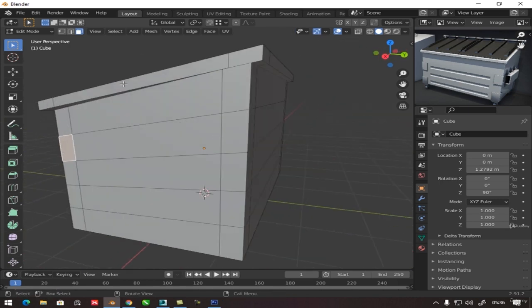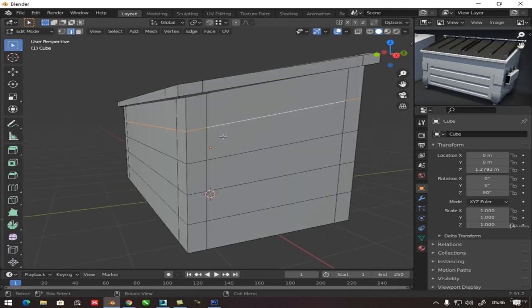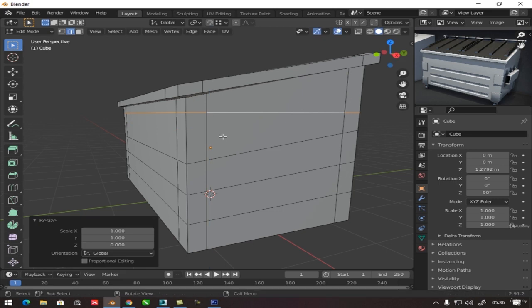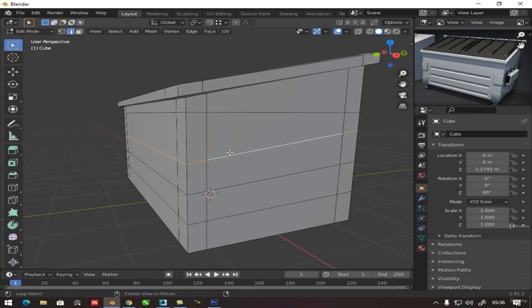Now, in this face, I'll get this face, but it's inclined, so I'll press this looping, SZ. Same thing here, Alt click does the looping, and here I press Shift R, so it will repeat the command.